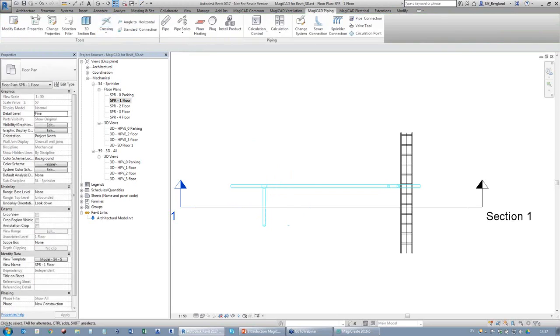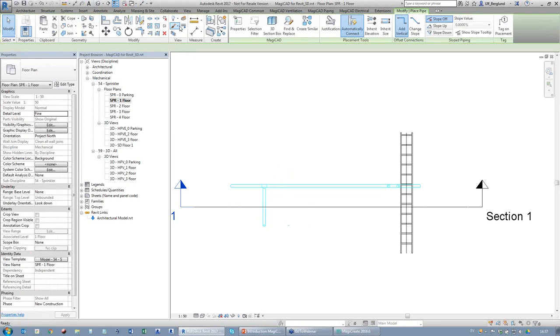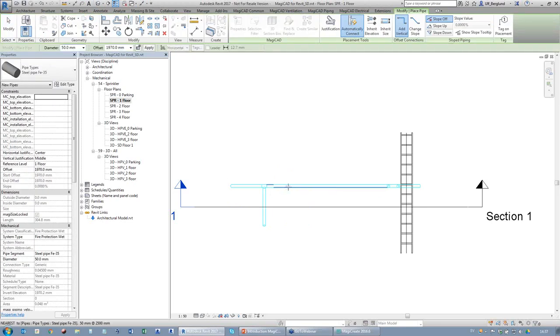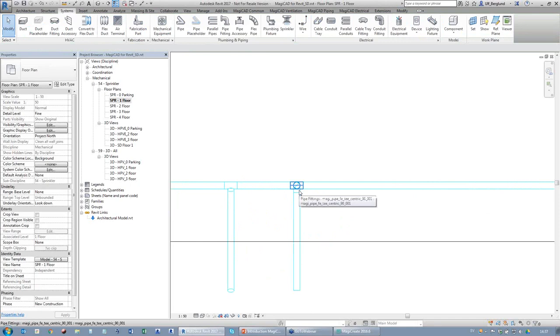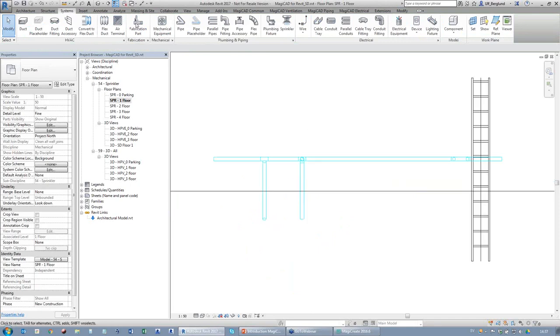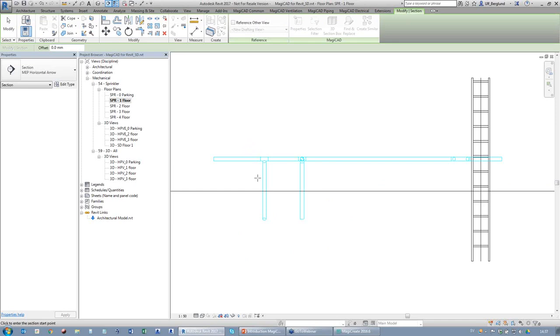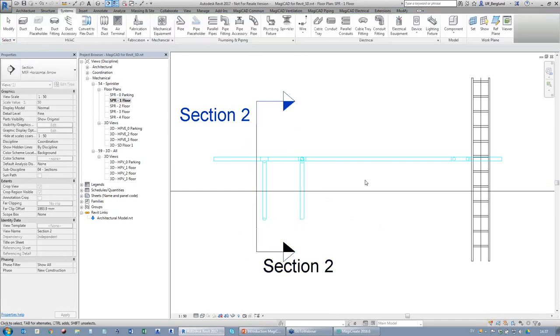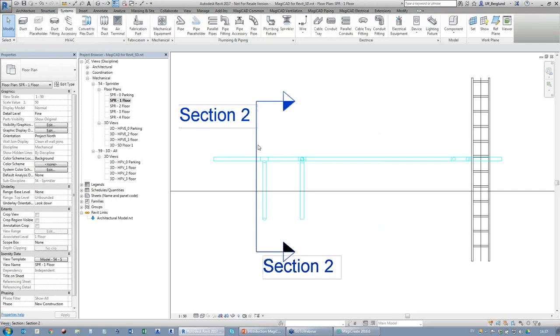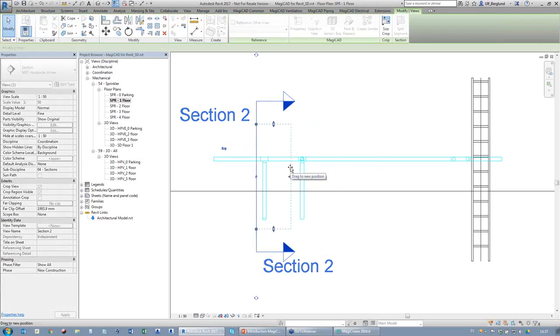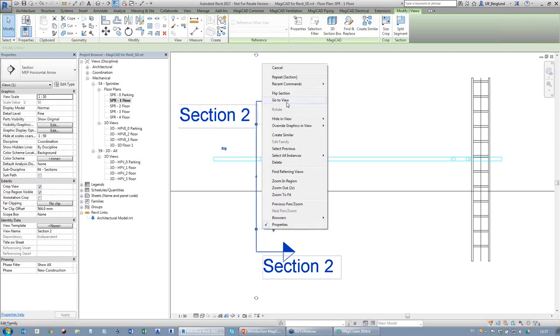The difference here is that if we are using a Revit pipe, if I start from this one, I just inherit the heights and then I go to 2,000 and then I go out. Then Revit will make this with a 90-degree from scratch. The only way of getting the look that we have, let's see.